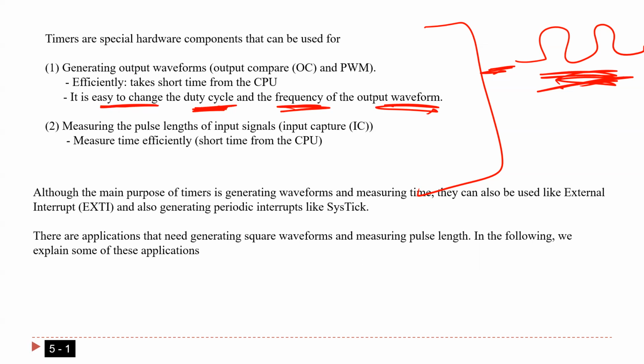Anyway, also you can, in a very easy way, change the duty cycle, you can change the frequency, and this is needed in some application. I'm going to explain the application shortly. Okay, so this is one thing, and by the way, if you are going to use this way, we call it output compare, or you can say pulse width modulation.